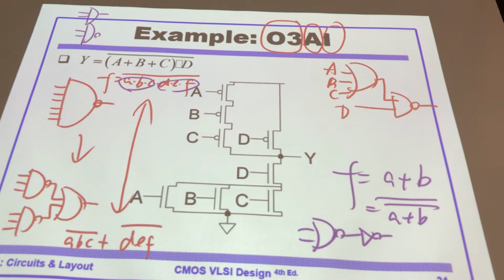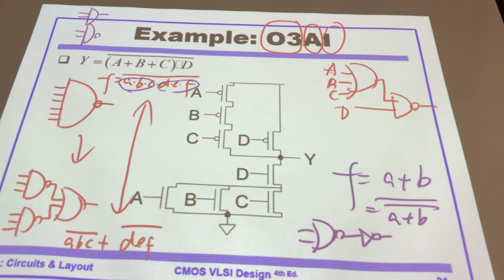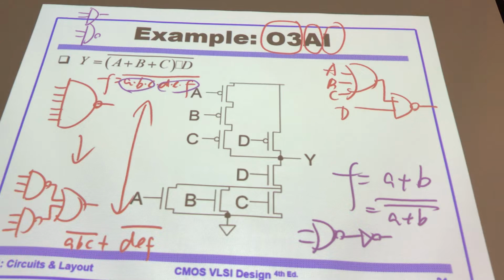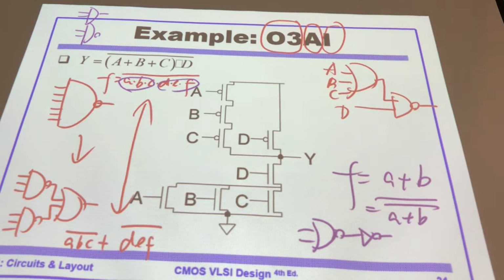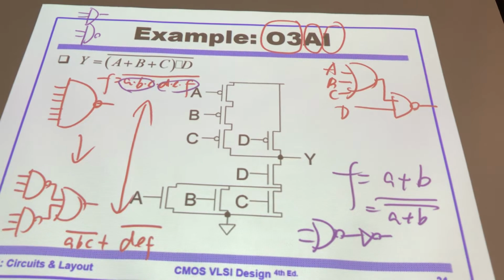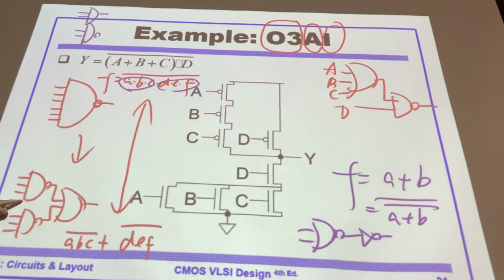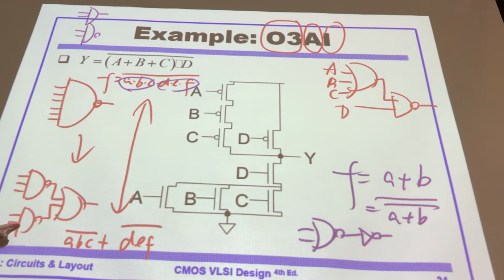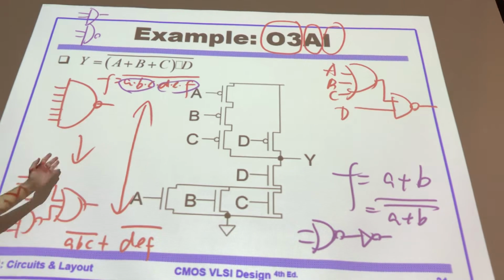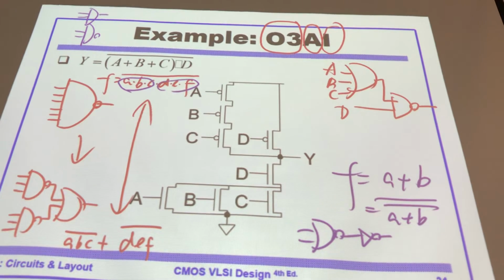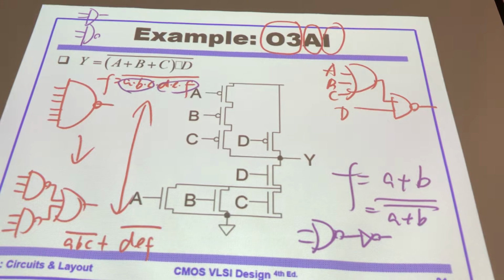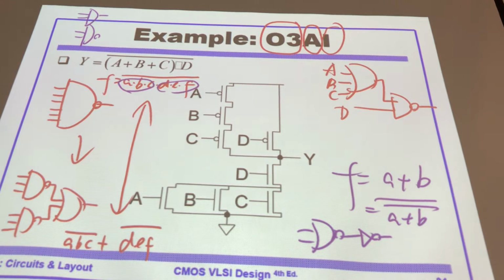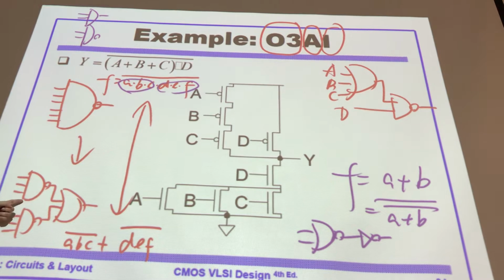Can we do 4 input and 2 input here? Is it better or is it worse? What do you think? It's worse, because the 4-input gate is going to be slow. And furthermore, even though it's faster, there are 2 levels, and these 2 are in the same position, in the same state, and this one is slower than the other.